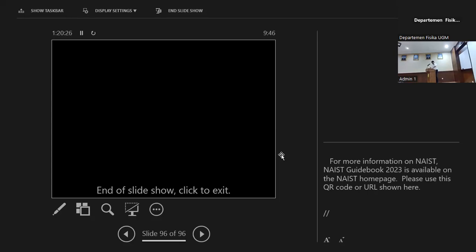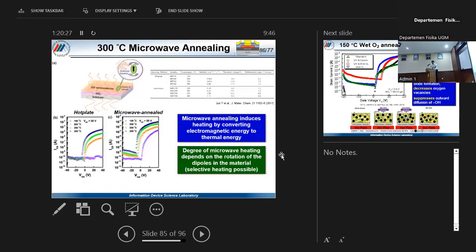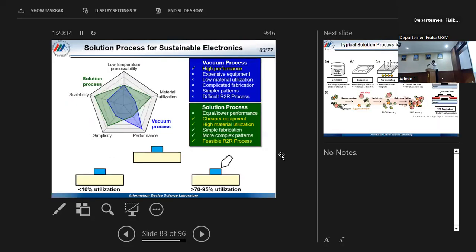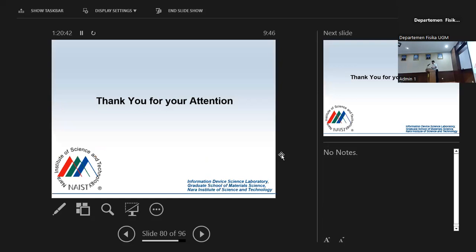And for the second question, unfortunately, I don't have the slide here, but the question is very good. So you're asking if it's only at the surface, right? The important part of the laser radiation is the wavelength and the extinction coefficient of the material. Depending on the extinction coefficient of the material, it will dictate how deep the laser will interact with the material. Aside from that, the wavelength also controls how it will interact with the material.